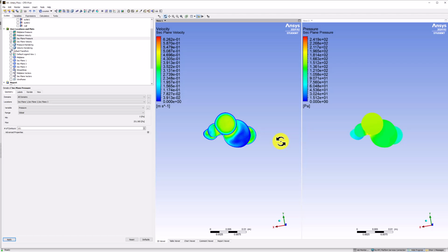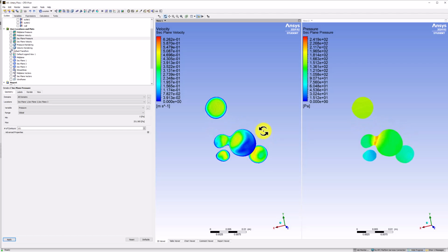Near the inlet, we can see the boundary layer development along the sides. The profile is approximately radially symmetric. The pressure, however, seems to be constant along this plane. Near the branch, the velocity contours show that the profile begins to skew, as seen previously. In the pressure contours, we can see the high pressure stagnation region, but the pressure is otherwise constant across the plane.